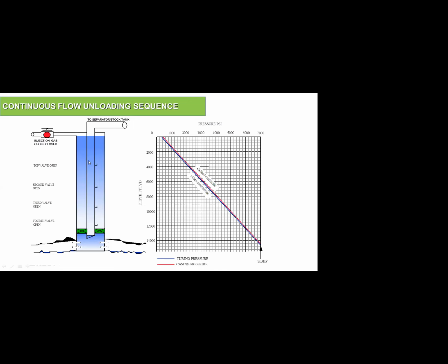So I can go there with coiled tubing and nitrogen and do unloading. I remove the fluid here until gas can enter here and produce, or I use something called unloading valves. I introduce many valves. The objective of these valves is to help, step by step, to unload or remove this fluid until my gas reaches the point at which it will be injecting. I will show it here with this graph, and also with a demo.